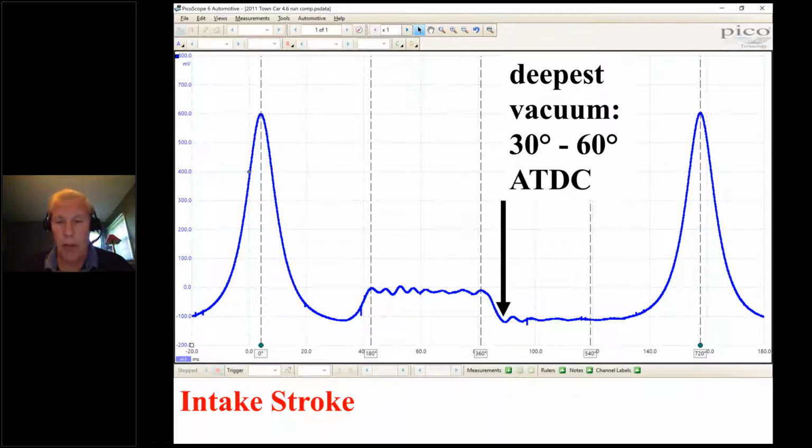You look at this point in your analysis and you just start making a measurement. You know, where did that point occur on this engine that I'm working on? And after you've done 10, 100, whatever, you'll have a feel for the numbers. So that's where my numbers come from. It's kind of a feel. But again, I think I can use that point as an indication, confirmation that there's a problem with cam timing.